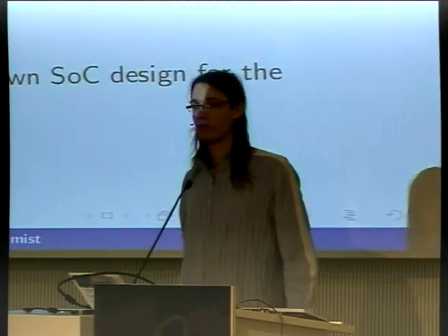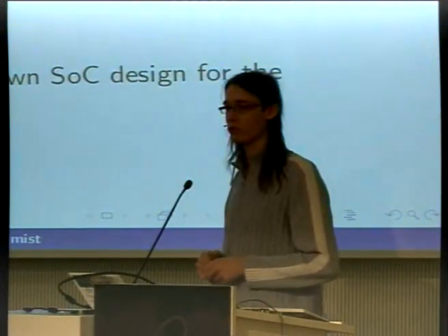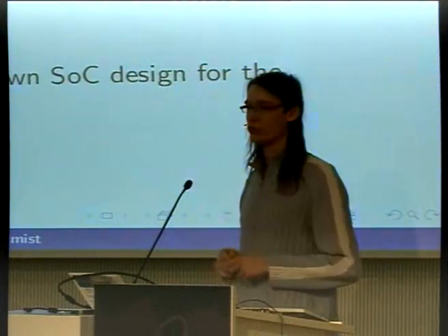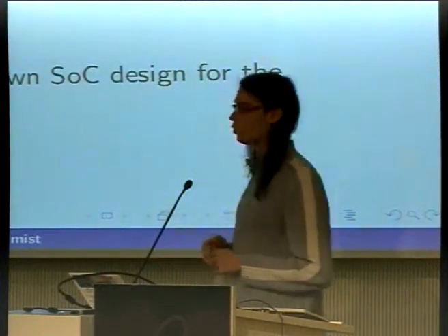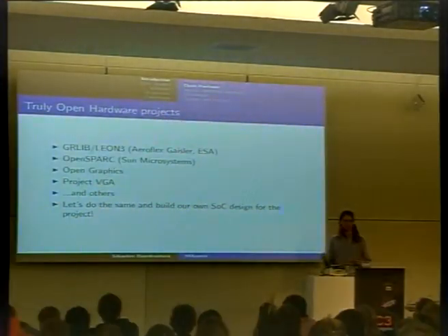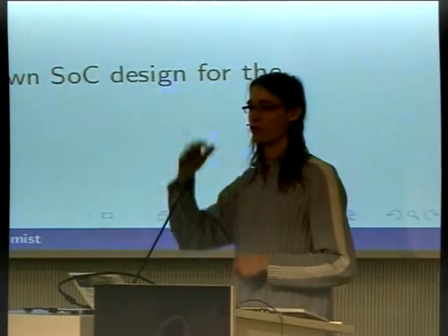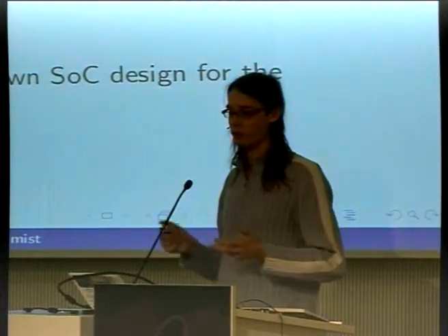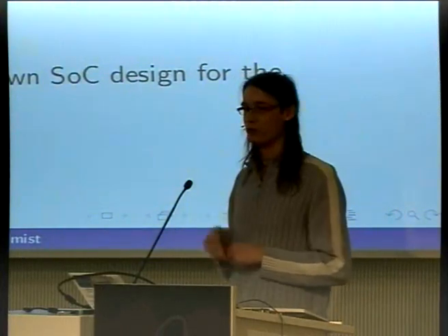There is OpenSPARC. Sun Microsystems is quite open source friendly, and they have released the source code for their SPARC processor in Verilog. Unfortunately, it's very hard to use OpenSPARC yourself because you need very big FPGAs. OpenSPARC is a very complex design, which has many optimizations, and sometimes when you are doing FPGA, it's better to have a simpler processor, which could run faster, because when you implement all the features which are in OpenSPARC in an FPGA, you get very complex logic functions with many levels, and the clock frequency goes very low, and it also eats up many FPGA resources. So OpenSPARC is not very accessible to hobbyists.